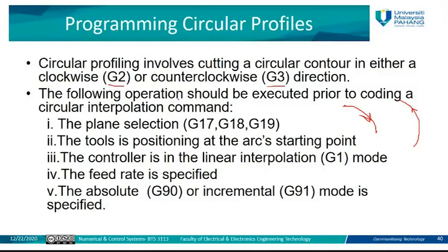There are some operations which should be executed when you are going to use G2 or G3. You have to use G17, 18, 19 to define the plane. This we already mentioned before. For a counterclockwise or clockwise circular profile, we need to define which plane we are working on. Is it XY? Is it XZ? Is it YZ? So you need to define which plane you are working with.